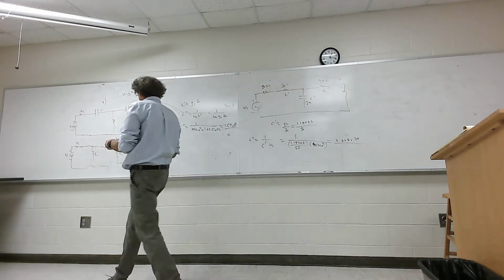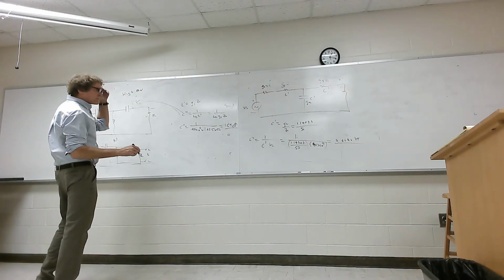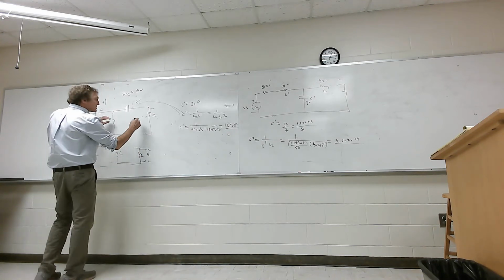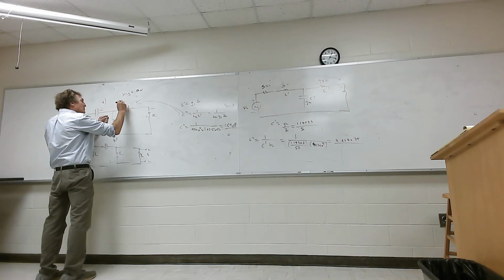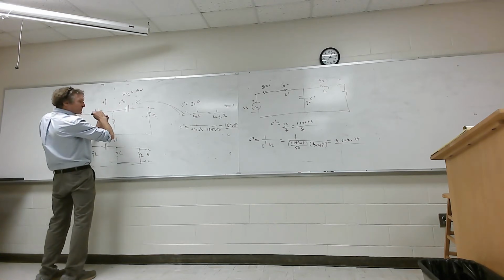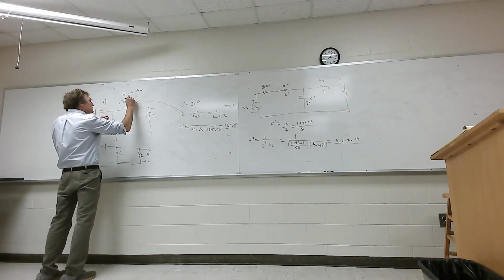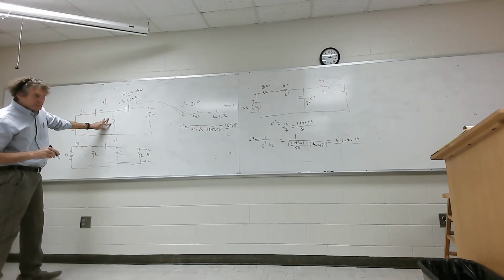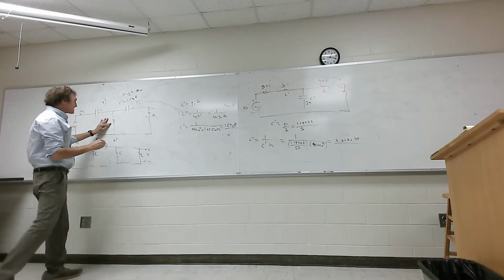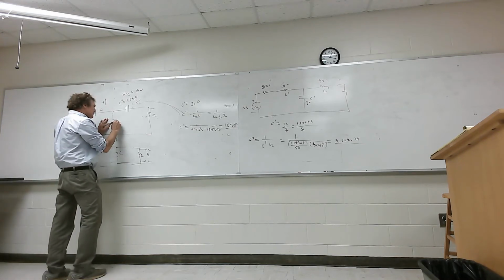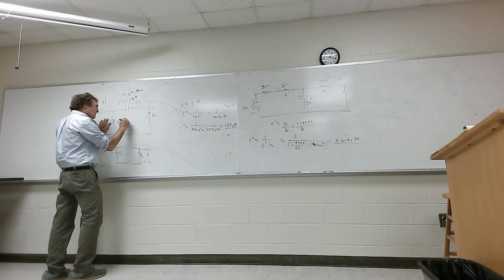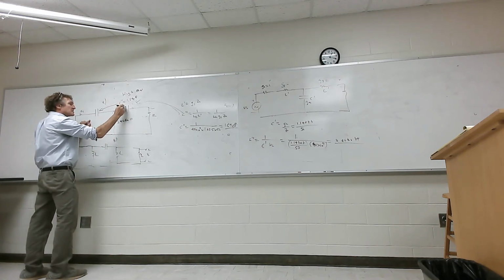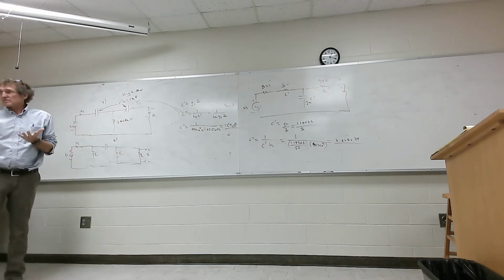So, this would be the value of the capacitor right here. The C double prime would be equal to 1.54 picofarads. And the value of that inductor would be 3.468 nanohenries. And this would be the same value here as well, isn't it? So that's the T filter.